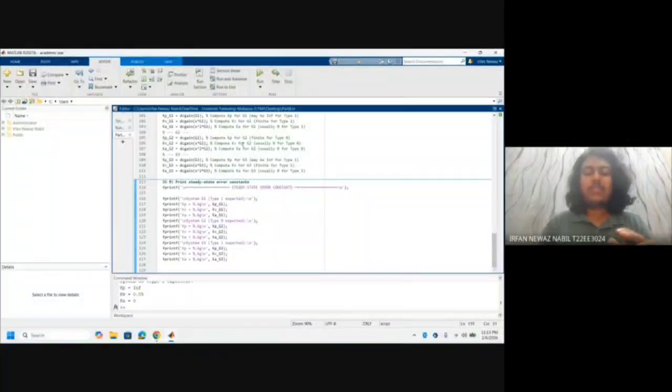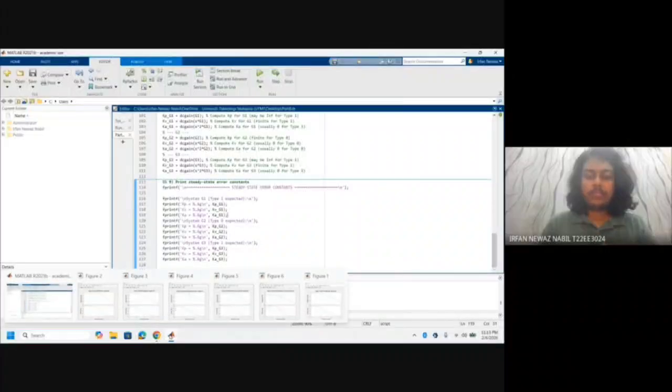In this part of the project, we apply frequency domain analysis to evaluate the stability, robustness, and steady state performance of three unity feedback control systems G1, G2, and G3. Using both plots, we determine the gain margin, phase margin, gain crossover, and phase crossover frequencies, and then relate these results to system type and steady state error characteristics. Figures 1 to 3 show the manual Bode plots, whereas figures 4 to 6 verify the results using MATLAB's margin command.